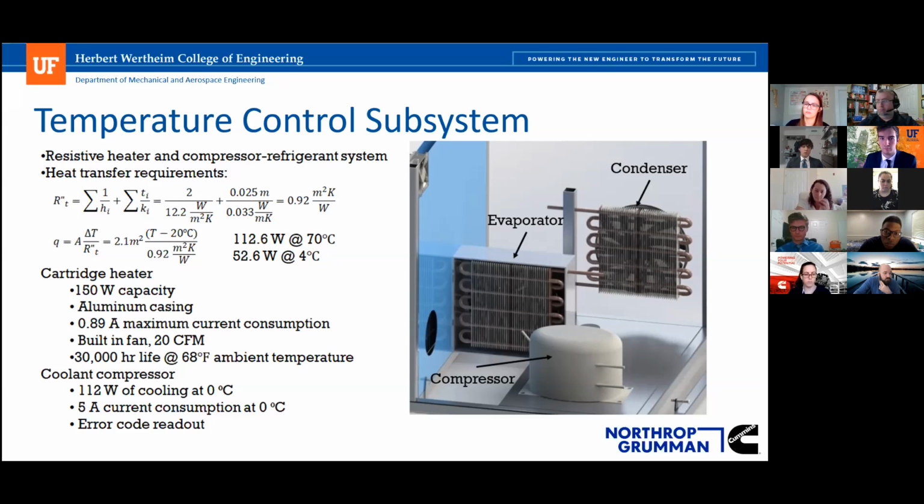The cooling is a compressor-based system pumping R134A. It's rated by the manufacturer to provide 112 watts of cooling at 0 degrees Celsius, which is below the functioning temperature, so we're well within the factor of safety. It draws 5 amps of current, and it has error code readouts for compressor leaks and for problems with the temperature measuring system, which allows for easier troubleshooting.